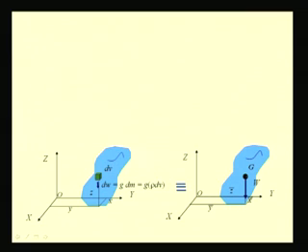So, if this concentrated load W has to be equivalent to all these differential weights dW, then the sum of the moments of these forces about say this axis OX has to be the same as the moment of this vector W with respect to this axis OX.